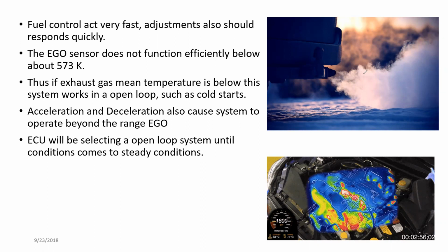The main disadvantage is that, since the engine is running as an open loop system, it's not getting any feedback from the signal. So to keep the engine running properly, it has to dump a little more fuel into the system to make it richer and avoid stalling.